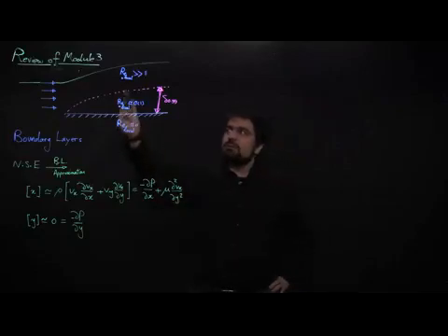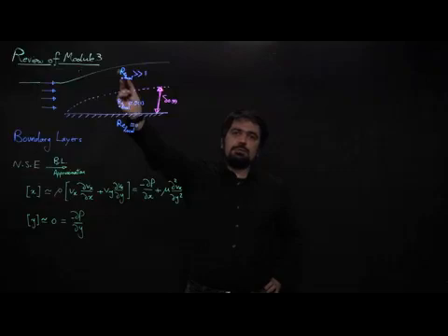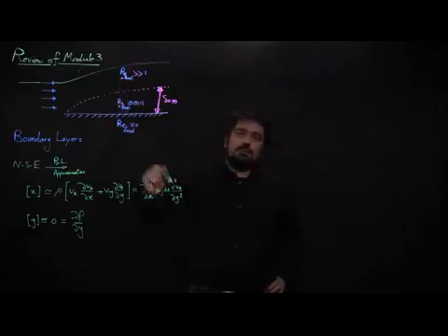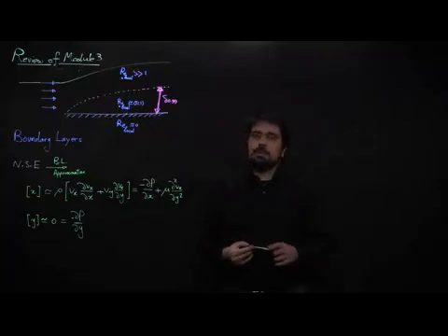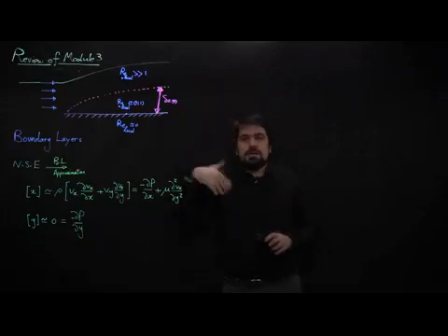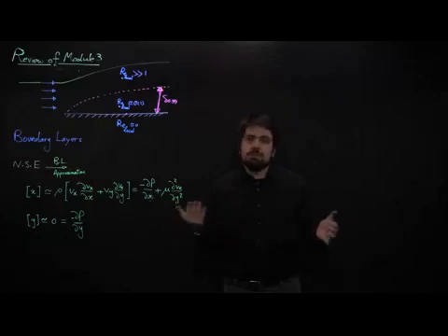If you take the ratio of inertia over viscous stresses for those points very far from the plate and construct a local Reynolds number, it will be much larger than 1. For example, for the flight of an airplane, for fluid elements way above the wing, the local Reynolds number can be of order 100,000, a very large ratio.